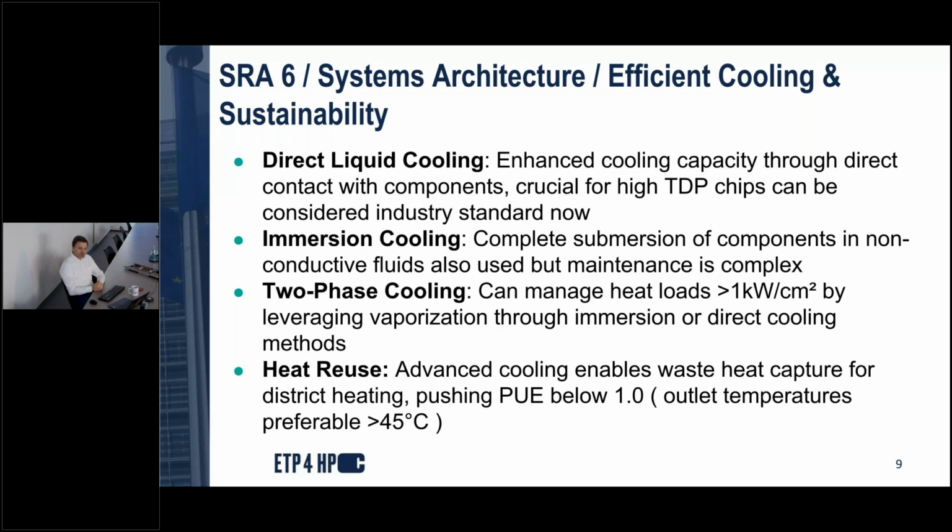Another method which is helping here is two-phase cooling. When you use water, the water stays liquid, but if we use a special liquid which can evaporate, then the heat which this fluid can take out of the system is much higher. This method can be used with immersion cooling or also with direct cooling methods, but it's still in development, especially for the direct liquid cooling method.